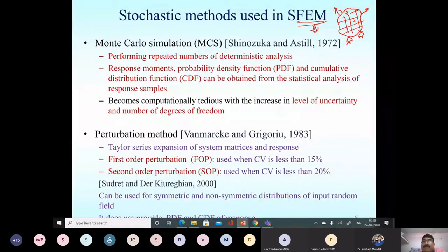Just making a finite element model for a single structure, a deterministic model, is cumbersome, because if you have stress concentration points or geometric irregularities, meshing itself is a very tough problem. The solver may be fast, but the pre-processing time for an FEM is computationally tedious. Think about the same structure with 10⁻⁶ or 5,000 or 1,000 analyses; the time taken will be very high.